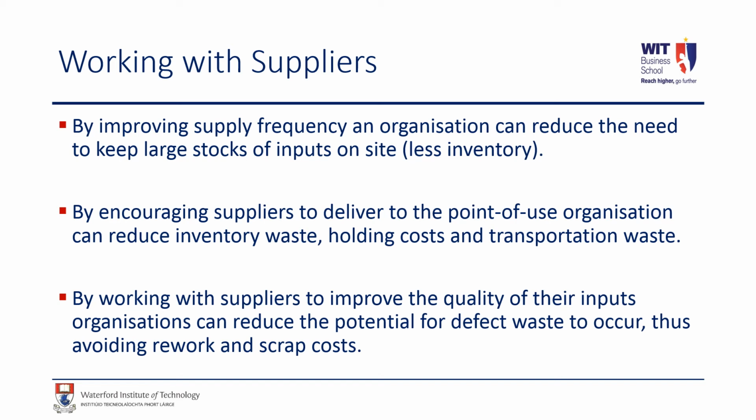We can also work with suppliers to improve the quality of their inputs. So if we can rely on suppliers to deliver high quality inputs, it reduces the need for maybe our testing of those inputs, but certainly also reduces the potential for defect waste to occur. And this can avoid rework and scrap wastes.